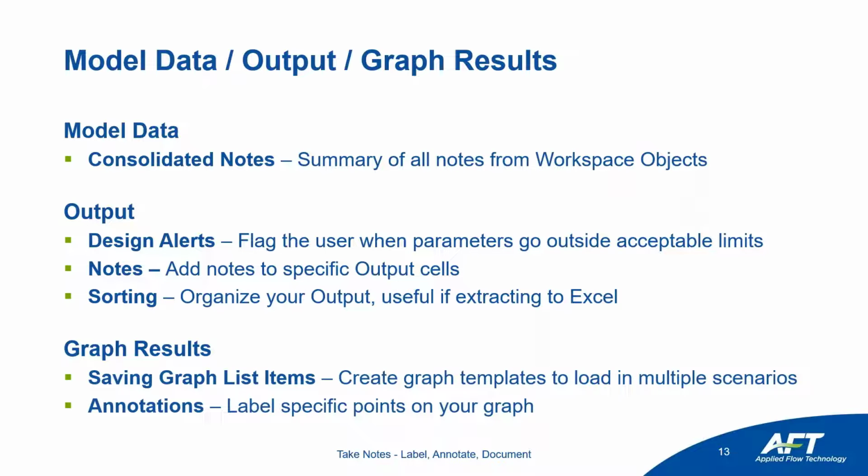The last one we'll talk about here is our graph results. And we'll show, one, how do we save our graph list items? So if we make graphs in a particular format, when we make other changes to the system, it will automatically reload that graph. And then also, how can we annotate our graphs to make it more clear what's happening? If we spent time on an analysis, it doesn't have to be a description in a report. We can point it out directly on the graph.